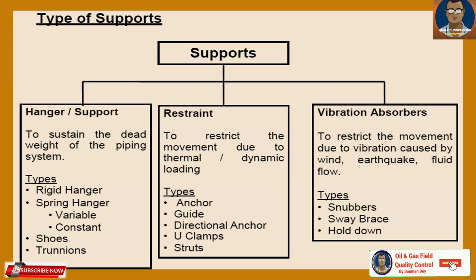And vibration absorbers restrict the movement due to vibration caused by wind, earthquake, or fluid flow. They can be of a few types like snubbers, sway brace, and hold down.